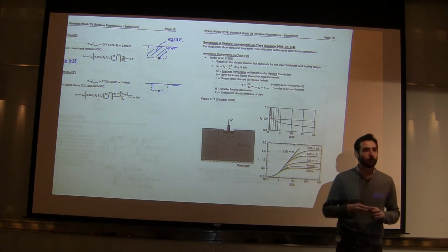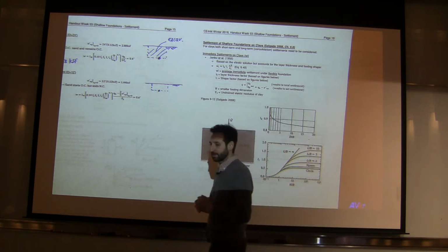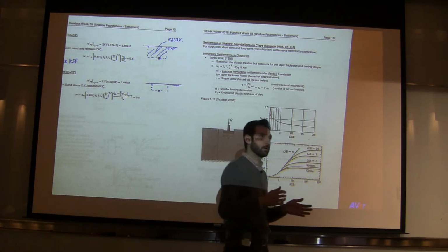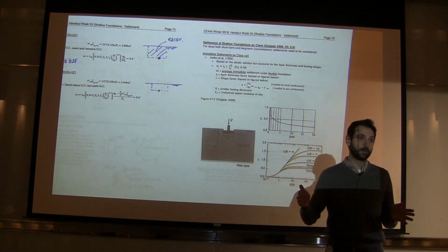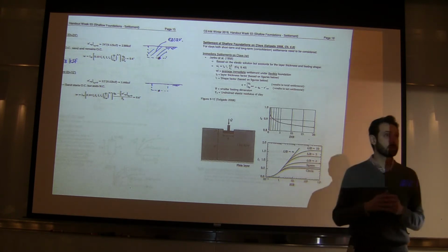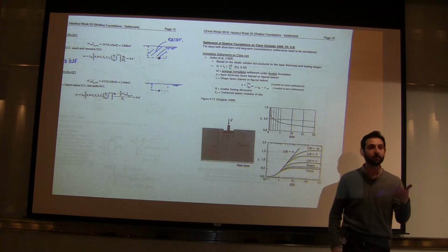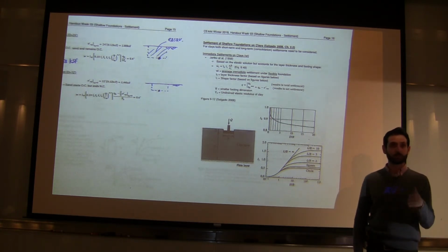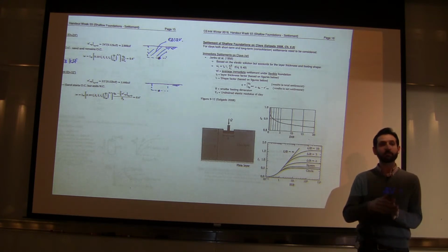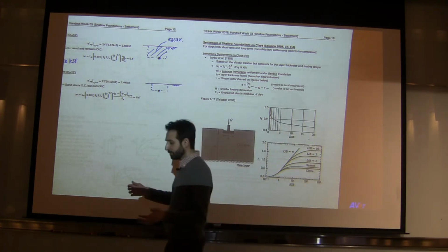Okay. So, we talked about the sand settlements and the time dependency of it, which we usually don't talk about in terms of something being time dependent. But it turns out that there are all these different factors of creep, a little bit of secondary consolidation, and the dissipation of pore water pressure, and the distortion in sand particles that results in some dependency on time. So you saw in the previous examples that if you get 2 inches of settlement immediately after the construction of the building, you may get an additional inch of settlement after 30 years. And 30 years is a pretty long time. So that's what we get for sand.